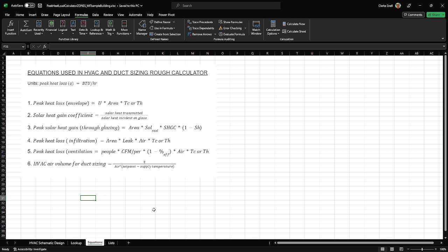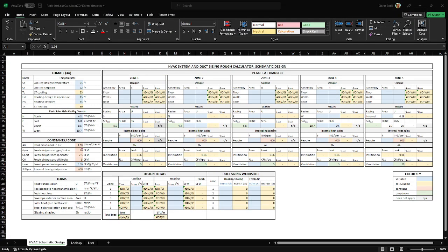We get that from the leakage rate, the square footage of the exterior surface of the envelope, a change in temperature, and then how much energy is carried in that air. Maybe that's a little confusing, but that's why it's here. We're calling it air in the calculations. It's something we have to use in the equations in the spreadsheet.